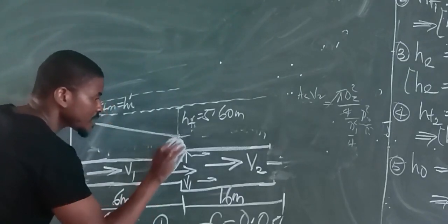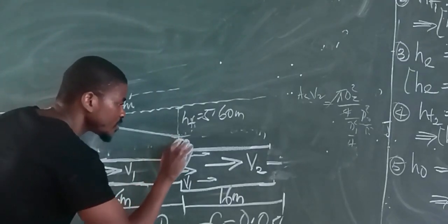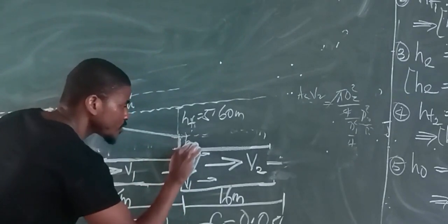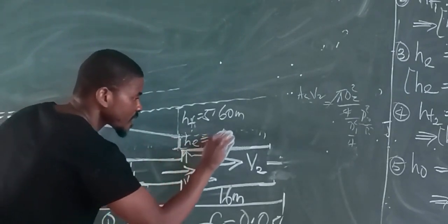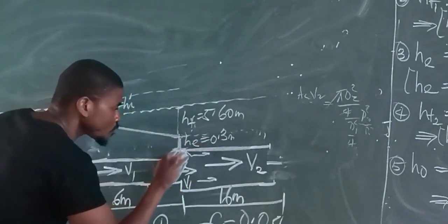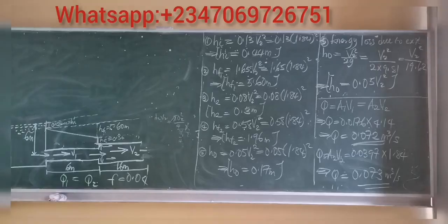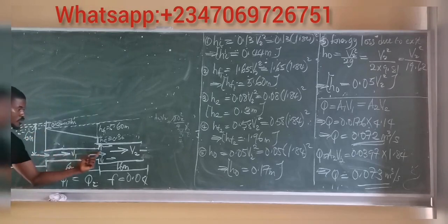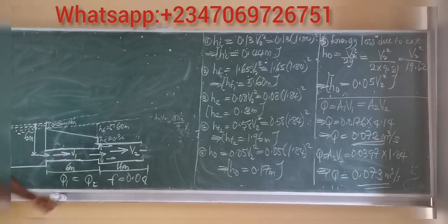Measure at 0.3. Now, this is head loss. If you trace this point out, this is head loss due to sudden enlargement, 0.3 meters. So you join these 2 points together, you have this. That's the enlargement. So you're seeing that we are reproducing almost what we have in the original diagram. So it becomes head loss due to sudden enlargement, and you have that.